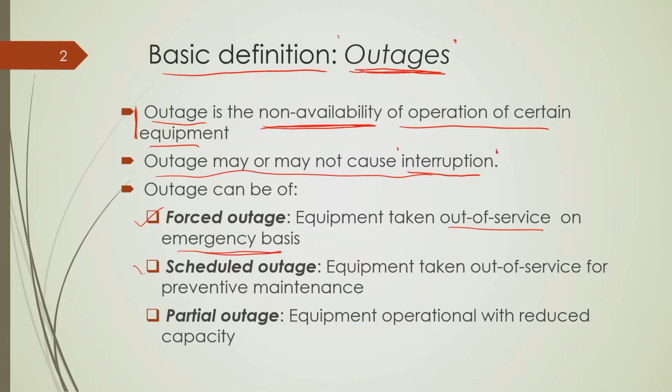There is another called scheduled outage, or planned outage, or preventive outage. This is basically to take out a certain equipment for preventive maintenance. Many times if you visit any substation or power plant, you will see the operators can understand with their experience that a particular equipment is getting faulty and is not performing at its full potential.